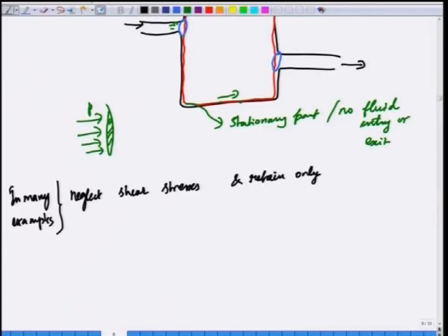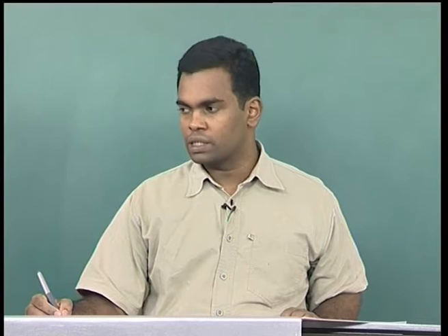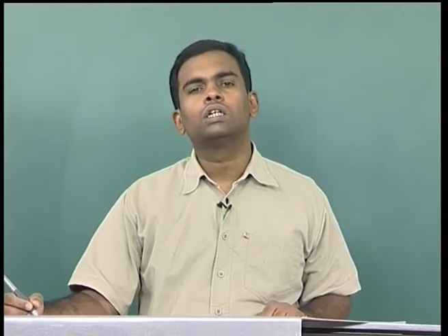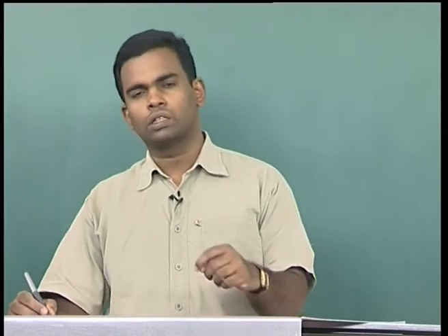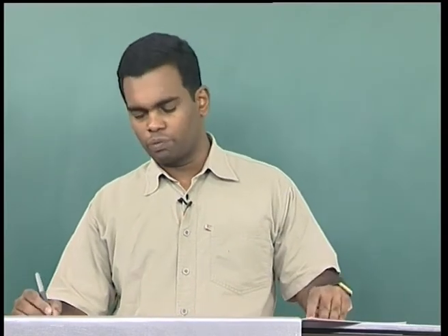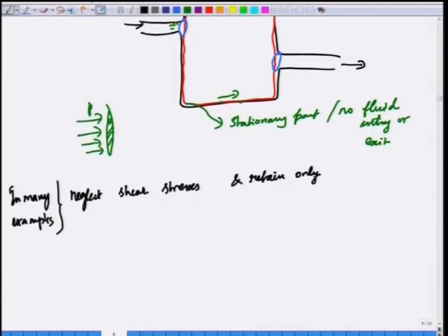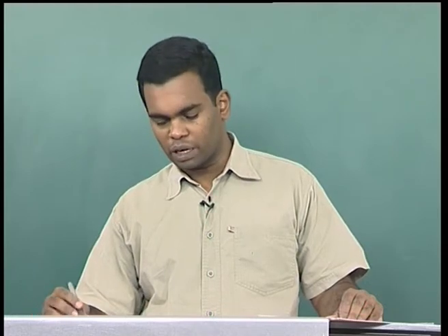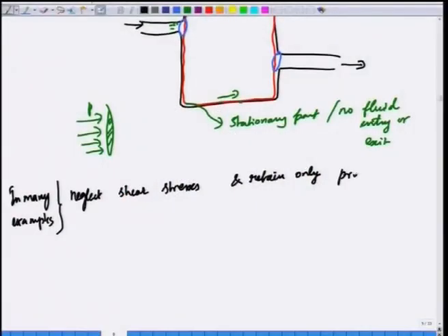One has to look into the context and then make a more judicious decision on whether shear stresses are in fact negligible or not. But in most cases it turns out that one can get a rough answer by neglecting shear stresses, just because we do not have much idea about the drag forces that are exerted by the solid surfaces on the fluid. So, we merely neglect them, but while doing examples I will try to indicate where one can actually get an estimate and so on, but right now we retain only pressure.